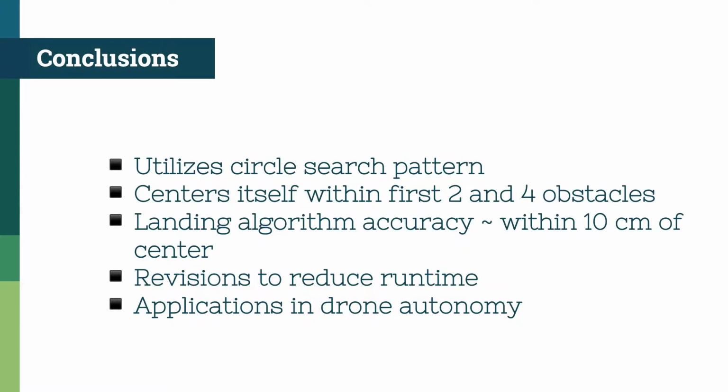So our algorithm currently is able to achieve an accuracy of within 10 centimeters of the landing site. This might sound large compared to the landing site itself, but if you consider that the drone is about 4 centimeters of a wheelbase, this means that small disruptions can actually move it very far from the landing site, and our compensation factors actually achieved a reasonable accuracy.